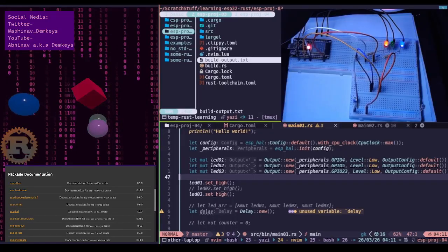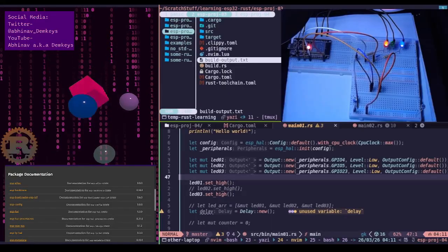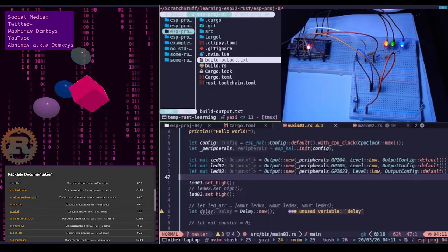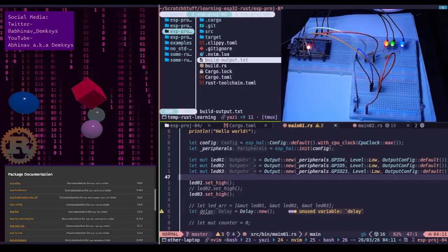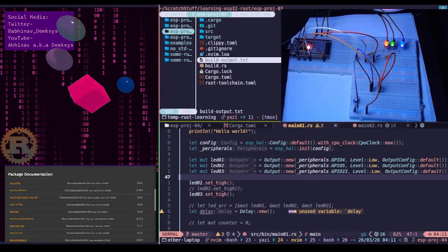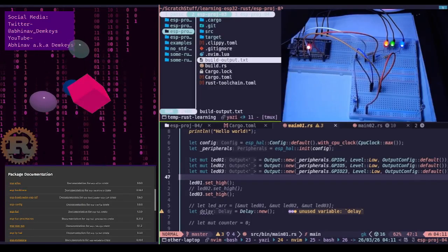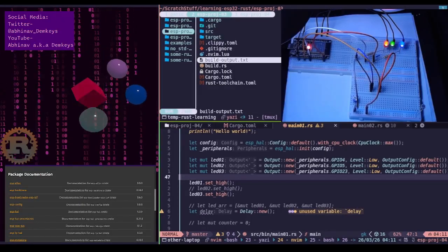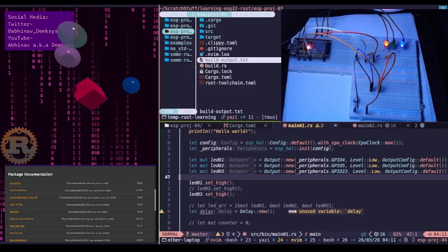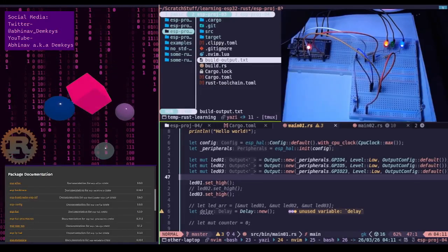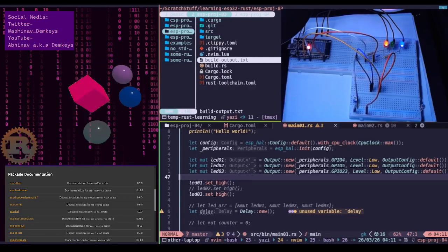It's a potentiometer, but we treat it as a voltage divider because of the way that it functions. Depending on where the wiper is currently at, we can consider them two separate resistors that are connected together. The ratio determines the resistance on one side and on the other side. That's what we are going to be calling our R2 and R1.